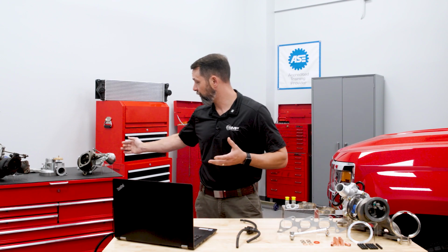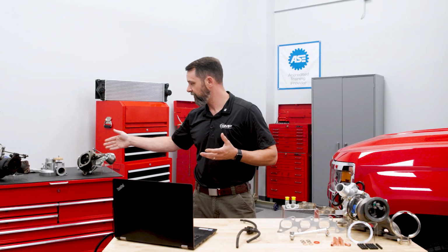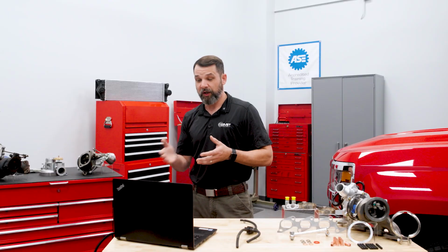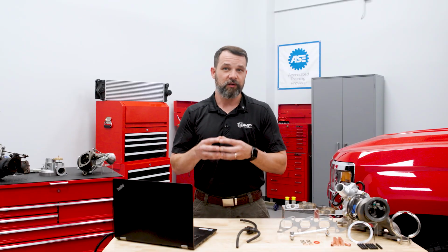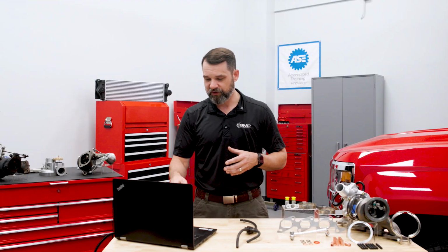So where we have a spring and a diaphragm on our pressure and vacuum operated, if the spring fails, obviously, we can get a little bit of play in the shaft. Well, if the actuator fails, you're not going to get any play at all. It's just going to not work. So it brings up another really good point, and so that's why I'm glad this question was asked.